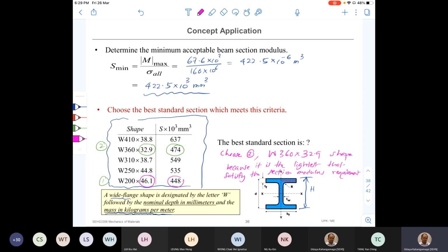Okay, and then we learned there's a relationship among the load applied, shear force developed, and the bending moment developed. So we learned that relationship. Using the relationship, given all the loads, now we can draw the shear force diagram directly, right? And also we can draw the bending moment diagram using the shear force diagram.